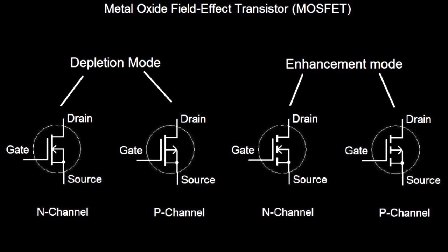So first we're going to get the transistor connected. My first pin is my gate, the second pin is the drain, and the third pin is my source. Now the current will go from the drain to the source. Be careful, because some of these transistors do have a diode in reverse bias. This is to protect the transistor from inductive loads such as those created by motors. So you want to make sure that you replace them exactly. So let's get started.